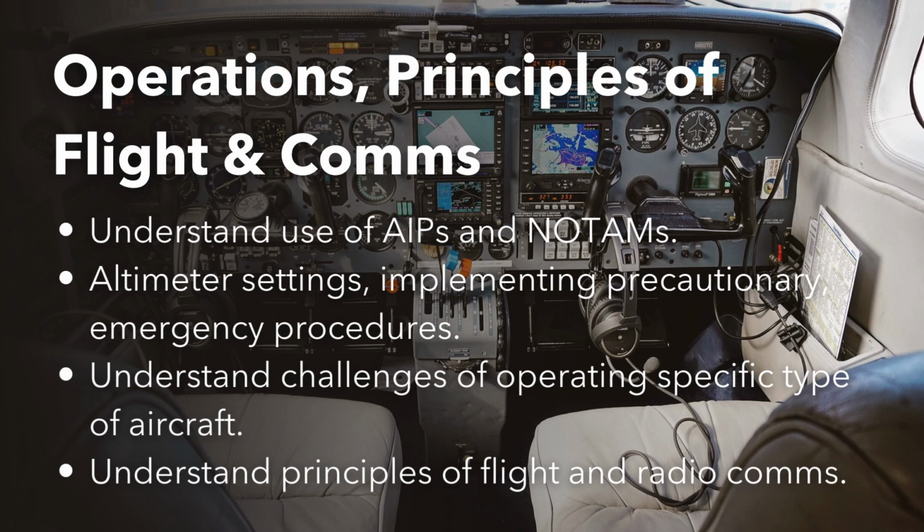Operational procedures cover a wide array of practices that are vital for commercial pilots, including the correct use of aeronautical documentation like AIP and NOTAMs, understanding altimeter setting procedures, and implementing precautionary and emergency procedures. Specific operational challenges associated with different aircraft categories, such as ground resonance or dynamic rollover in helicopters, are also covered. Additionally, applicants must be well versed in the principles of flight and radio telephony, including the standard communication procedures and phraseology used during VFR operations and the actions to take in case of communication failures.